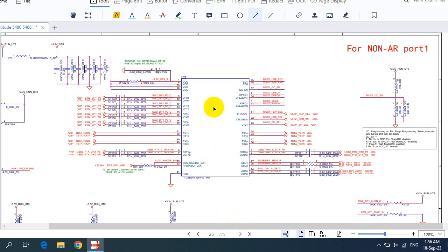For the IC, I want to add that you will find two references. This reference over here and another reference here. This reference is its reference in the motherboard. As you can see, we have here UT9. But this is the part number. If, for example, you find out that this IC is burned out or failed, you can replace it or change it using the same part number.